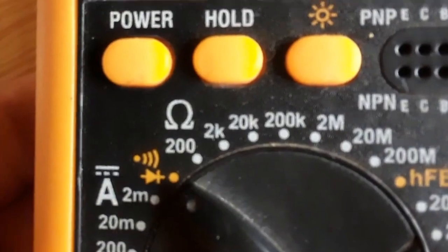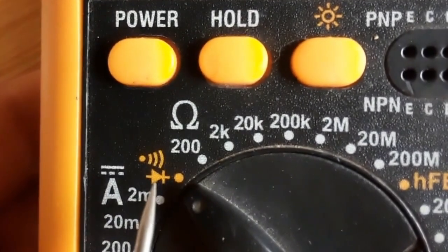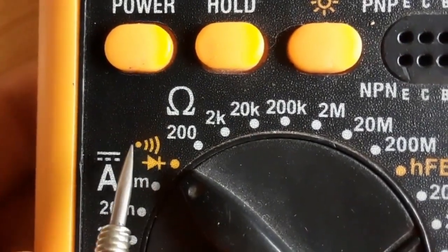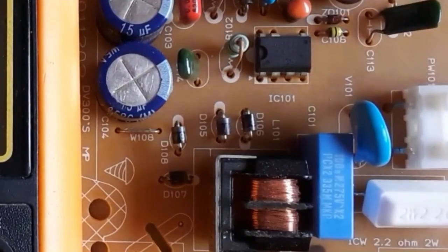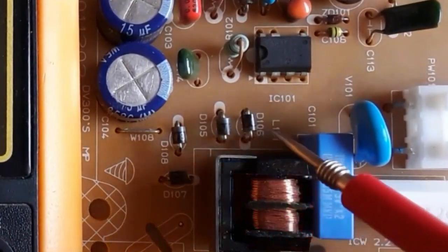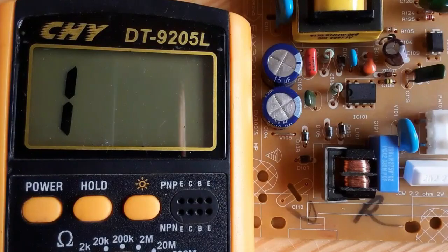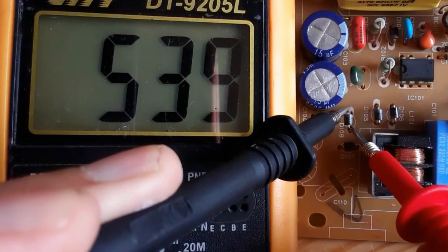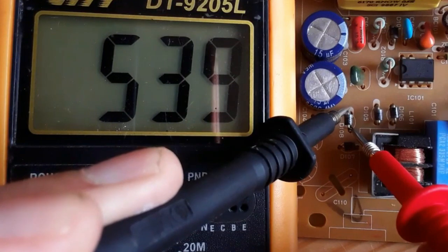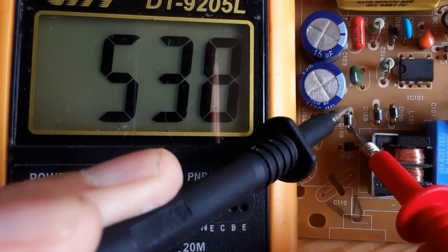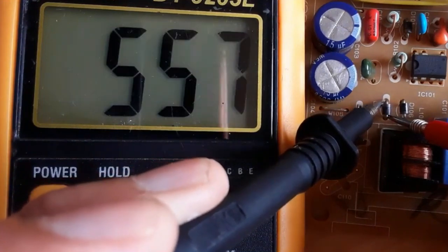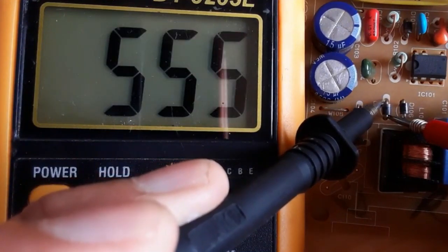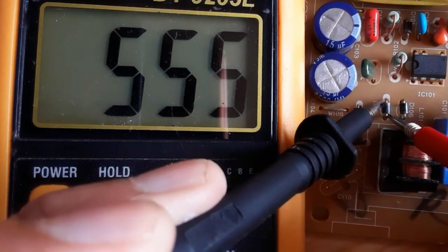We're going to use the multimeter to test these diodes, and we're going to select the diode option in the multimeter. Let's begin first with testing a normal diode or a standard diode in order to see the difference between both. Here we have a 500 drop voltage. Okay, let's check the other diode. As you can see, we have about 500. The drop voltage or the reading is about 500 for standard diodes.